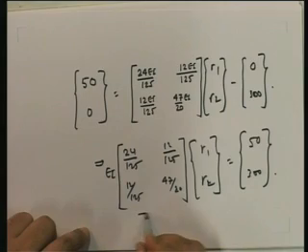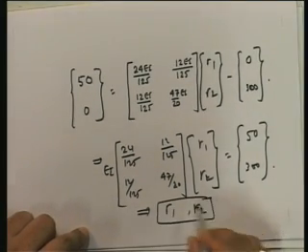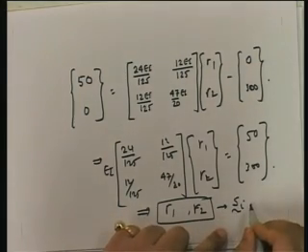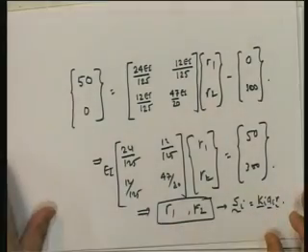So we solve for R1 and R2, from which we can find our S_i, because S_i is equal to K_i A_i into R. Once we find the member end moments, we can always draw the bending moment diagram. This is a fairly simple, specific problem, and therefore there is not too much in it.